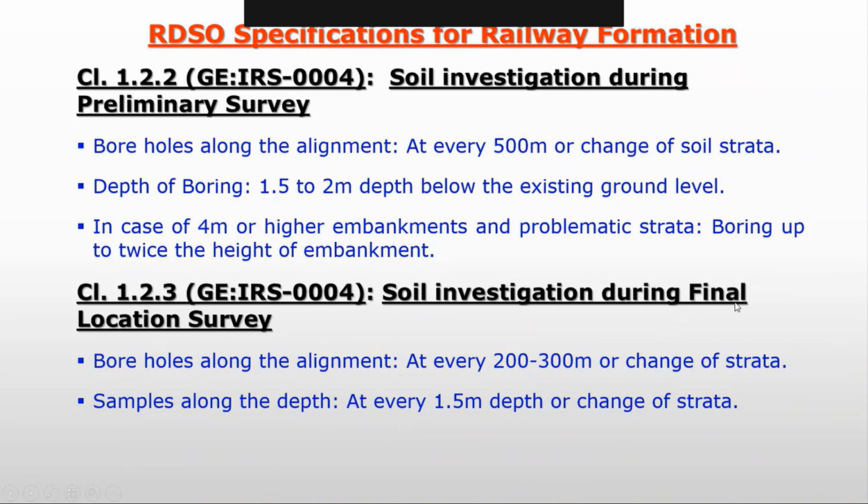For the final location survey, we have to take bore logs at every 200 to 300 meters, double of what we did during the preliminary survey. Depth of boring almost remains the same, 1.5 meters, or change of strata.